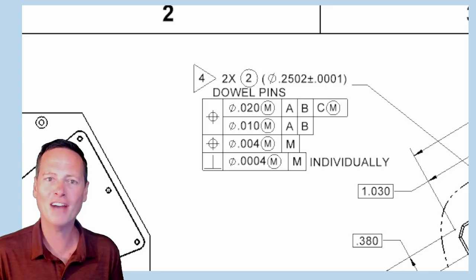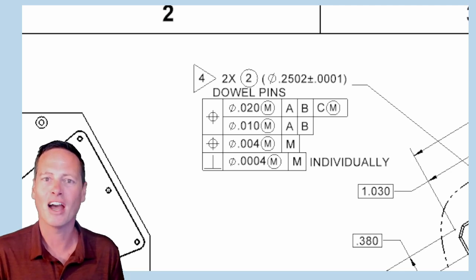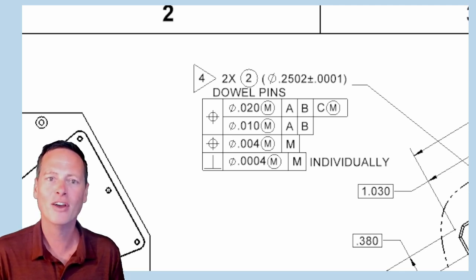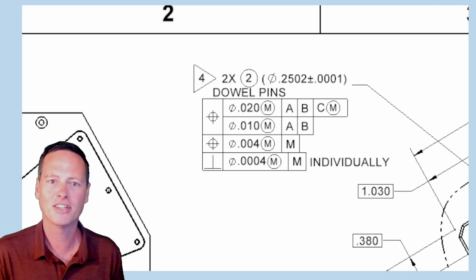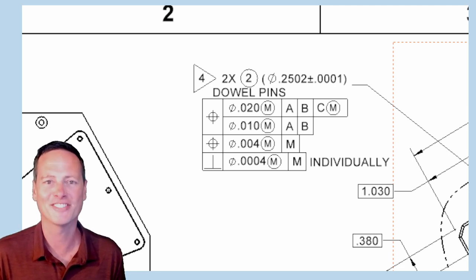Okay, so the composite position is a great way to refine the positional requirements of these pins within ABC. Then there's nothing new. I locate them together as a pattern now with the 4 thousandths. Okay, so that's 2 cylinder-shaped tolerance zones, 4 thousandths in diameter, located on their basic positions. This is analogous to plus or minus 4 thousandths pin to pin. And then, of course, perpendicularity, which I say applies to the individual pins, not the pattern in this case.